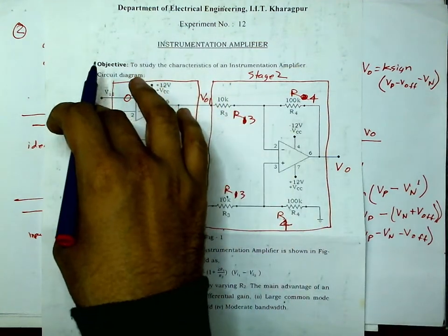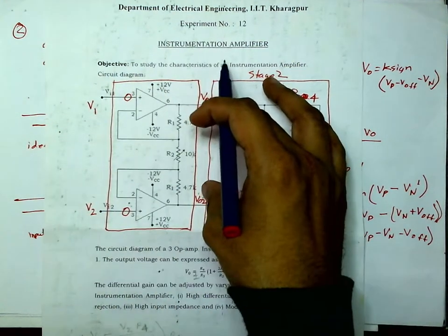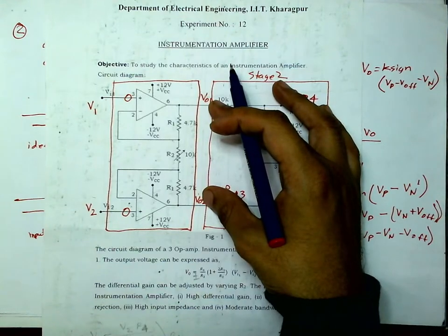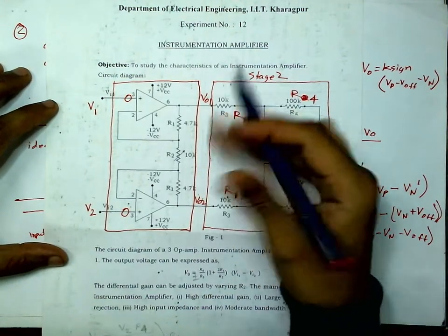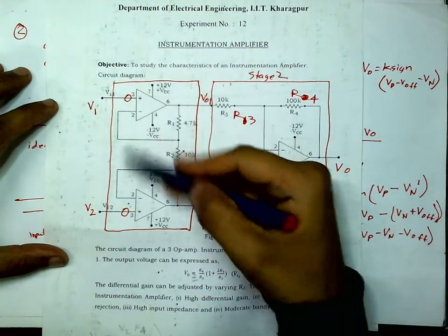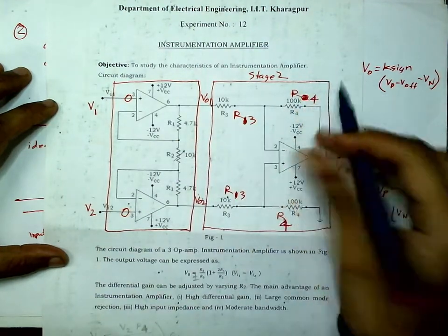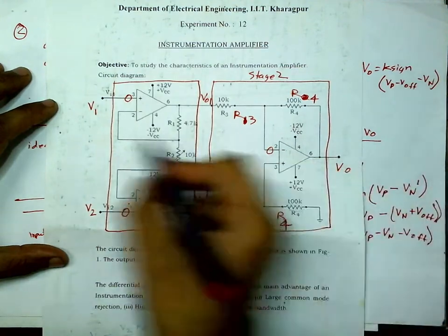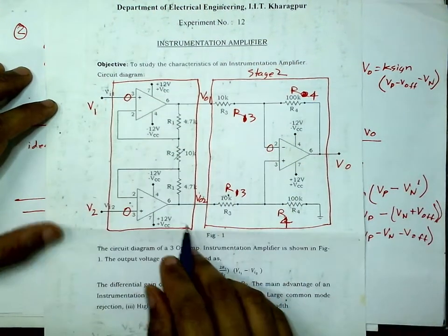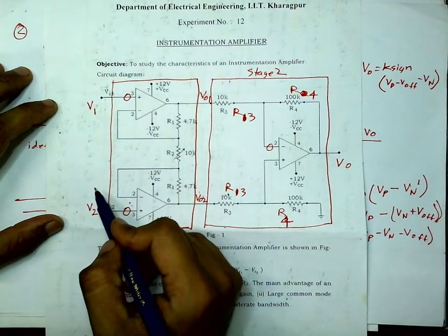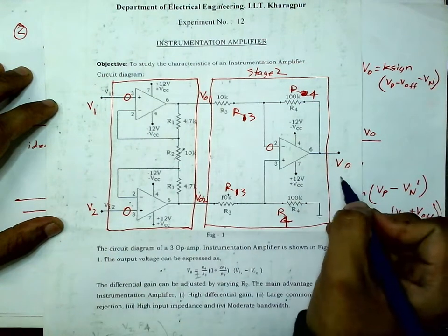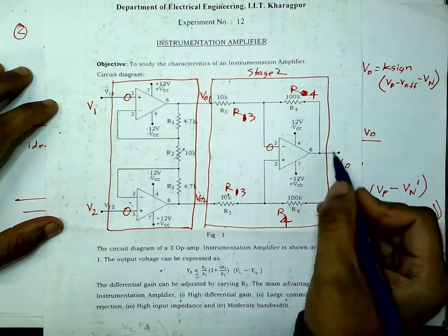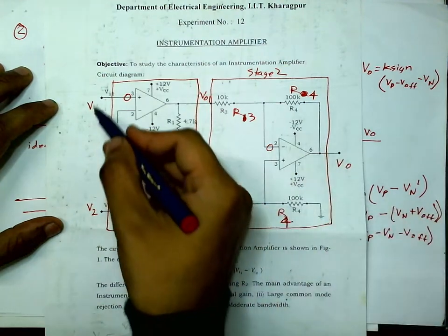In an ideal scenario they should also be the same, but they may not be because of these two things. And then you may still have some output even when these two are the same. So this is reason 2 why we can have a common mode gain although the two inputs are the same.